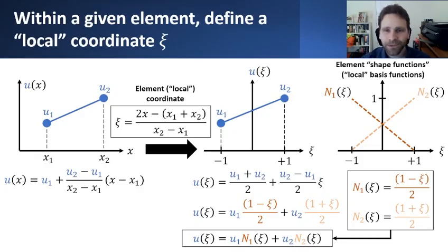It's also important to note that these shape functions are typically expressed in terms of the element local coordinate frame, in terms of this coordinate psi ranging from -1 to +1. So it's generally the case that when you're expressing shape functions, they are expressed local to one particular element as a means of interpolating nodal values, and which range over this particular element local coordinate psi.